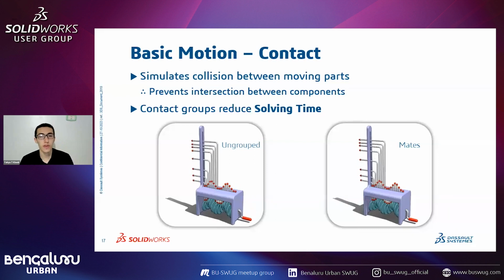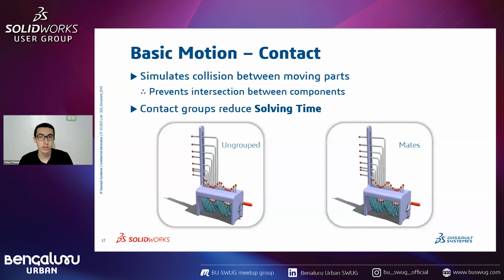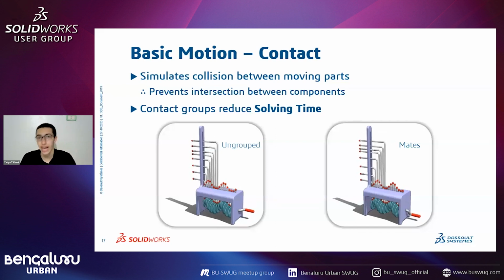So for example, if I want to take more things into consideration, like friction between components, and taking into consideration that this component is made of this material, therefore it may slide a bit harder or slide a bit smoother and that kind of stuff, that you can't easily do using animations, but you can easily specify that if you're making, let's say, motion analysis, you can specify everything in the contacts and how the components interact with each other.